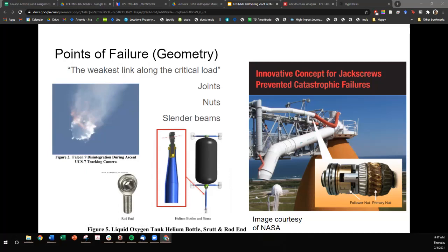Instead, wear could be determined by measuring the axial gap between the primary nut and the follower nut. So if this component starts to hug the follower nut, then you know that the primary nut has failed. Additionally, electronic and mechanical wear indicators were used to monitor the gap between operation or assist during inspection. These devices would be designed to generate a warning when the thread was worn to a predetermined thickness.